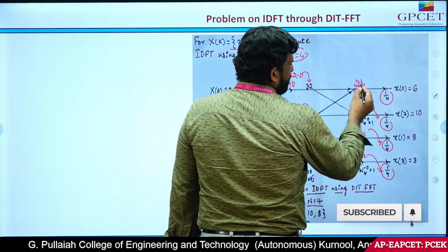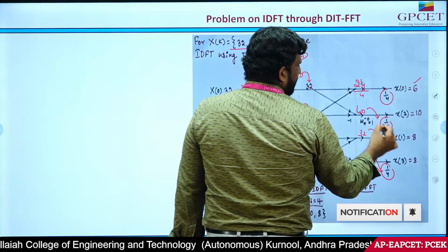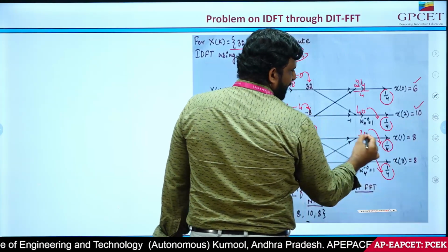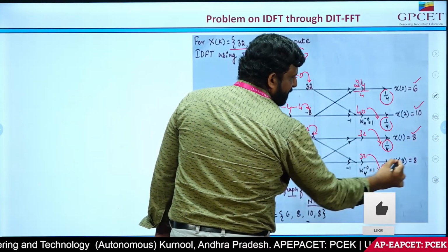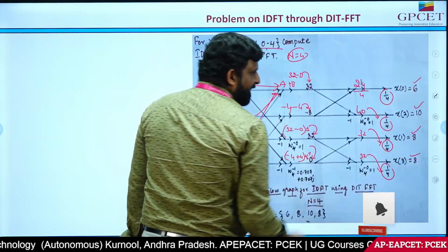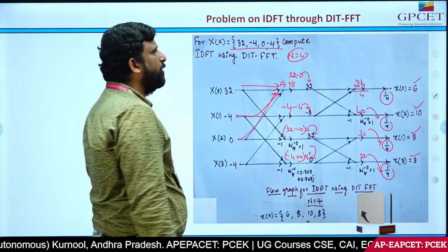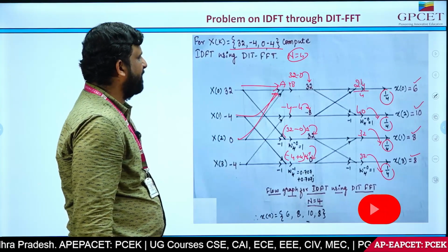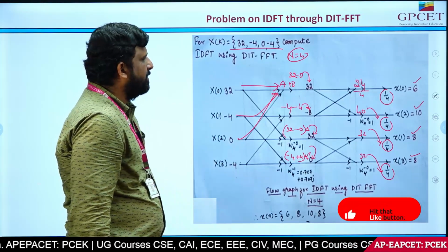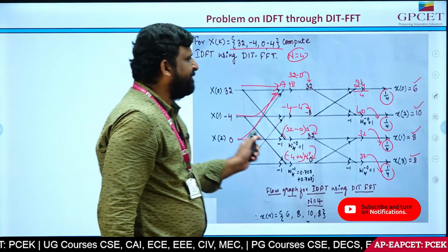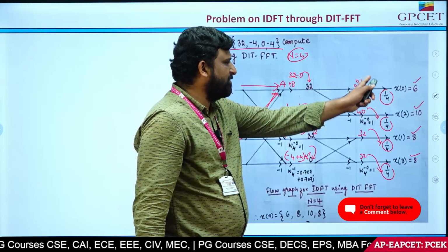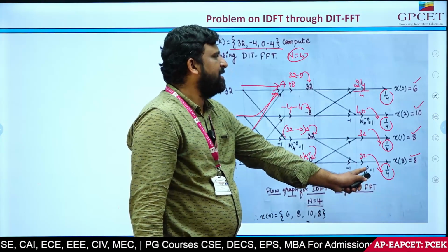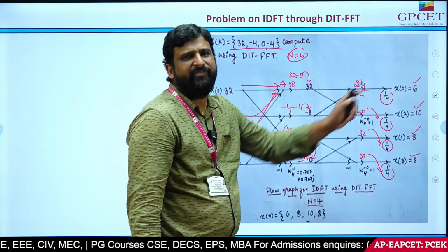So what is 24 by 4? I got 6. 40 by 4, I got 10. 32 by 4, I got 8. And 32 by 4, I got 8. So this is the finalized output that we get in the IDFT using DIT FFT. Okay, I think you got the answer. The process will be the same. Only the thing is that whatever answer you get in the final stage will be multiplied with 1 by 4.